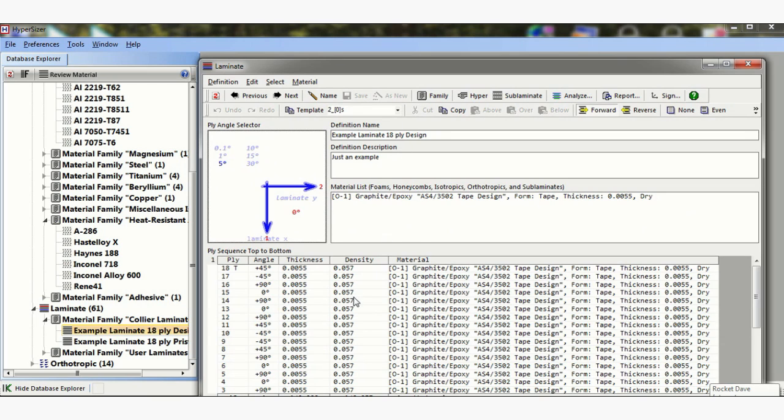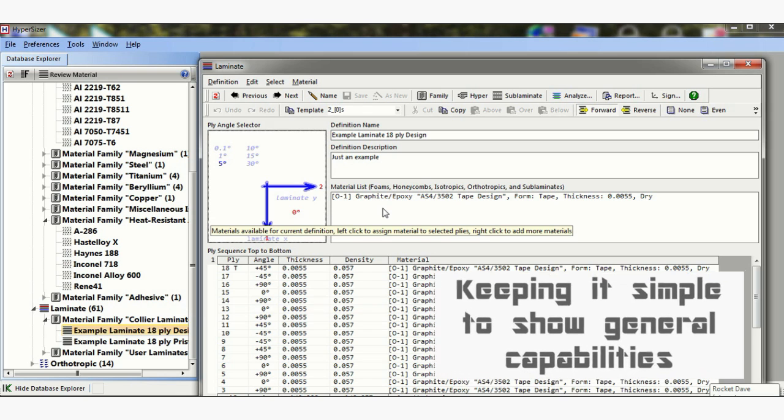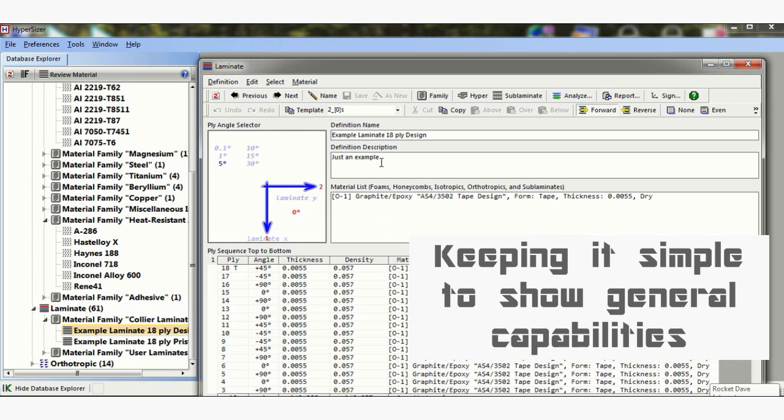So if we're optimizing composites, it's very useful for us to create some laminates that we would prefer to use with the layout rules per our corporation. A lot of corporations have different rules of how many 45s you can have in one sequence, etc. There's a lot of rules. Maybe we'll get time to discuss that later, but you can do the same thing, and you can edit these laminates and create new ones.